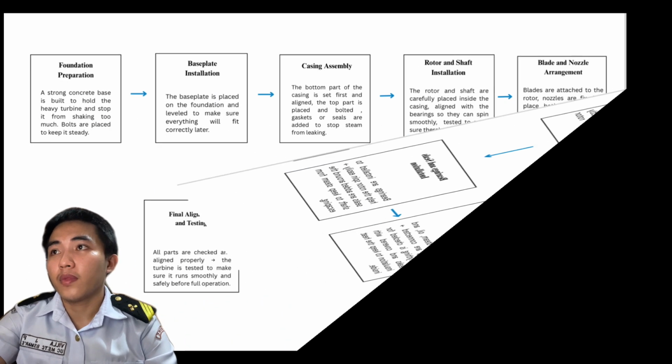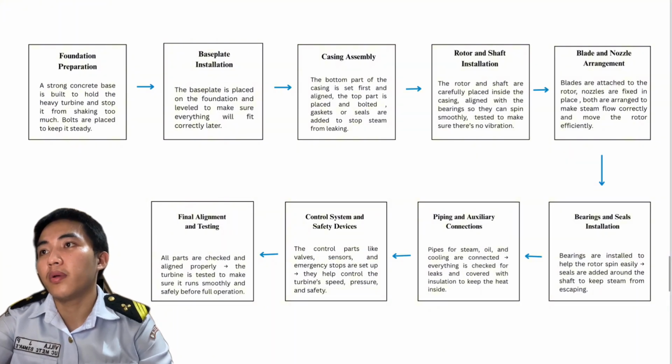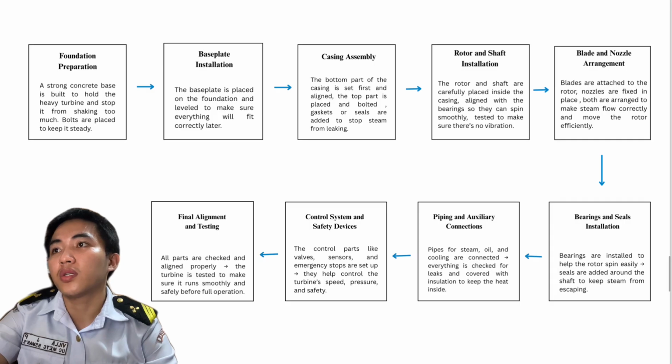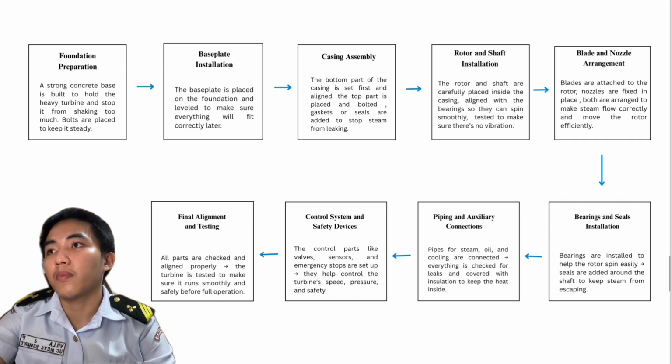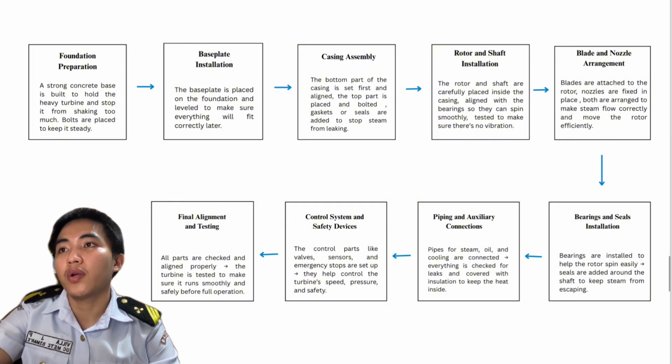So first step, foundation preparation. A strong concrete base is built to hold the heavy turbine and stop it from shaking too much. Bolts are placed to keep it steady. Base plate installation. The base plate is placed on the foundation and leveled to make sure everything will fit correctly later.